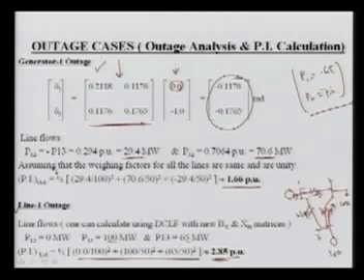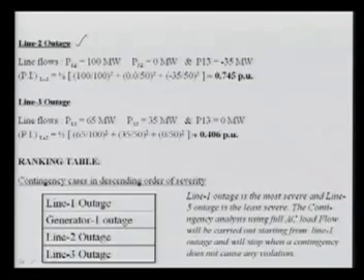So 0.65 will be flowing here and the remaining 0.35 will be flowing here. In this case also there is no need to form the B matrix again; we can simply use Kirchhoff's law, calculate, and we'll find these values, 0.745. Again we are using the PI for this outage. Similarly, for line outage 3 we can form it and we'll see this value.